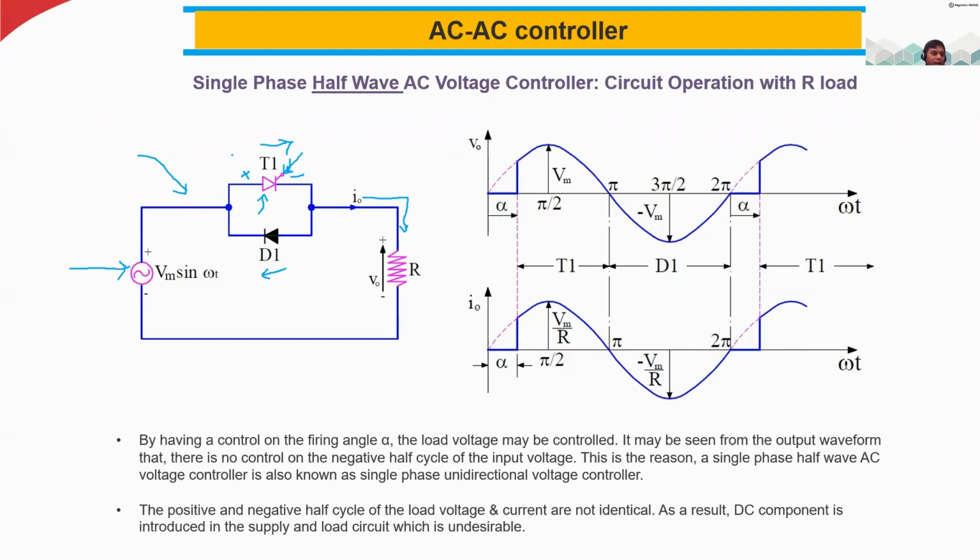Last week, I told you, if you apply the negative voltage to the anode and the positive voltage to the cathode, then this SCR will be in reverse biasing. That is called reverse blocking mode. And similarly, if you keep the forward bias, positive and negative, but do not apply the trigger signal, then this will be in the forward blocking mode. So forward blocking mode, forward conduction mode, reverse blocking mode: these are the three basic operations of this SCR.